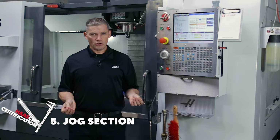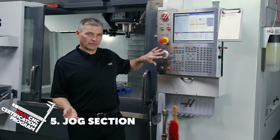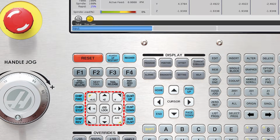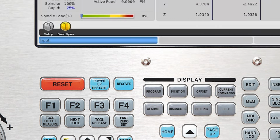In the mode section, we saw the handle jog key, which activates the jog handle. These 9 keys here in the middle select the axis you want to move when you're in handle jog mode. We're already somewhat familiar with the X, Y, and Z keys. Now, the reason there is a plus and minus key for each axis is for when you're using the jog lock key here in the middle. When you press jog lock, you'll see the jog lock icon come up at the bottom here.